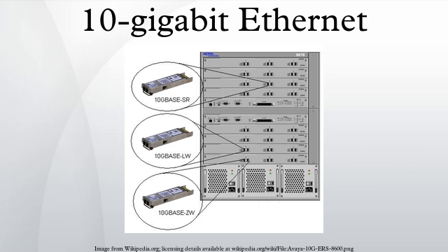Optical fiber. There are two classifications for optical fiber, single-mode and multi-mode. In SMF, light follows a single path through the fiber, while in MMF it takes multiple paths, resulting in differential mode delay. SMF is used for long-distance communication and MMF is used for distances of less than 300 m. SMF has a narrower core, which requires a more precise termination and connection method.